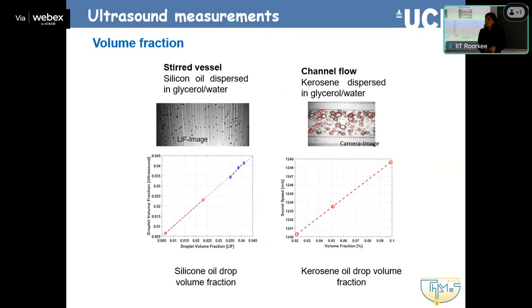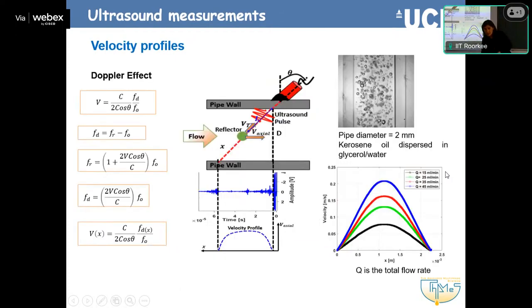So this is one way, and in a way one easy experiment, to get volume fractions, especially if your flow patterns are dispersed or anything else. We talked about annular flow, dispersed flow, plug flow, and to get it without actually seeing what's in there.